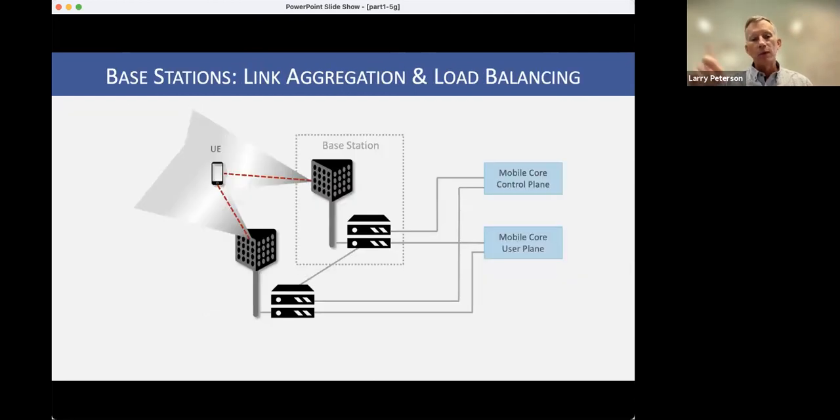So one takeaway from this is I think of these base stations, look at the dotted line I've got drawn, there's a base station. Think of that as a packet switch. It happens to have an antenna attached to it. So at one of its ports, it speaks radio, but the base stations are connected to each other to form a packet switch network overlay. They route packets to each other and they make decisions as to which base station is the appropriate one to deal with a particular UE, and that changes over time as UEs move and other UEs move into their cell, and so they've got work to do, so they hand it off. But think of it as a packet.